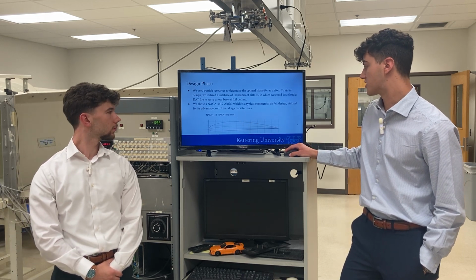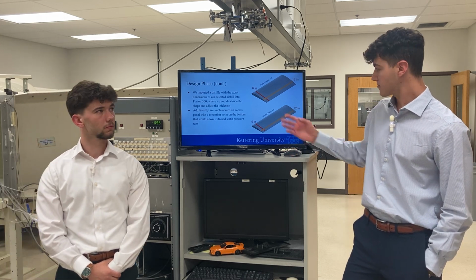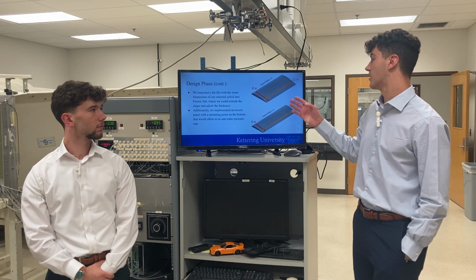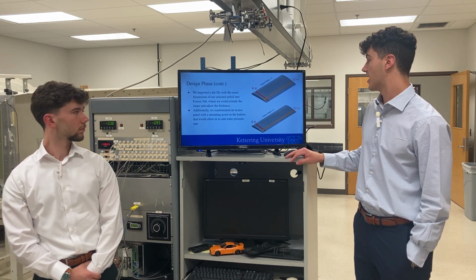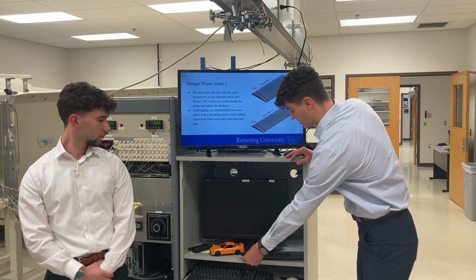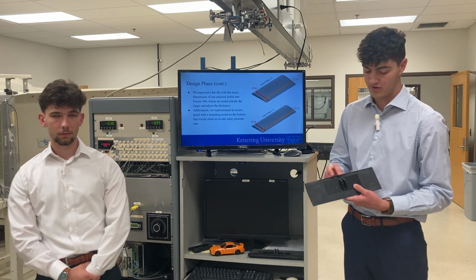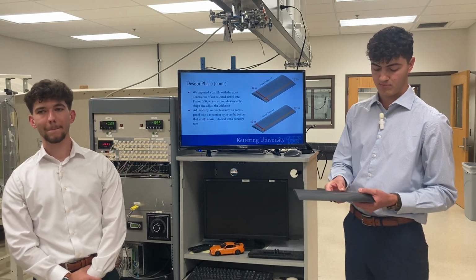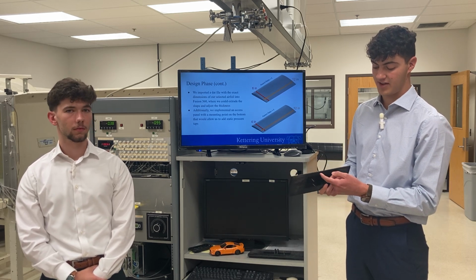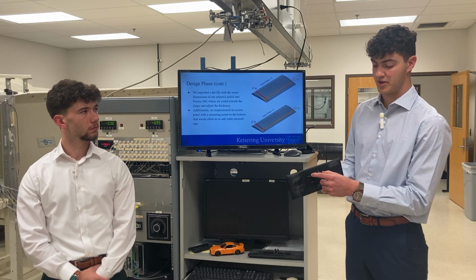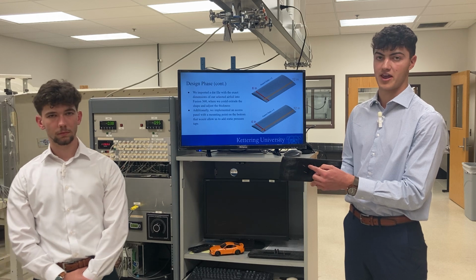So once we determined which one we wanted to use, we were able to import it into CAD. And basically, this allowed us to display that the aspect ratio is represented, like Matthew said, the span over the chord length. And then once we modeled the airfoils, we also implemented an access panel on the bottom side of our airfoils that we could use to put our static pressure taps through, as well as a stagnation tap through the front. And then our plan was to have a 90-degree angle within this access panel, because we basically have a pocket in here that we could use some soft tubing to create a 90-degree angle and then have that come out the bottom.